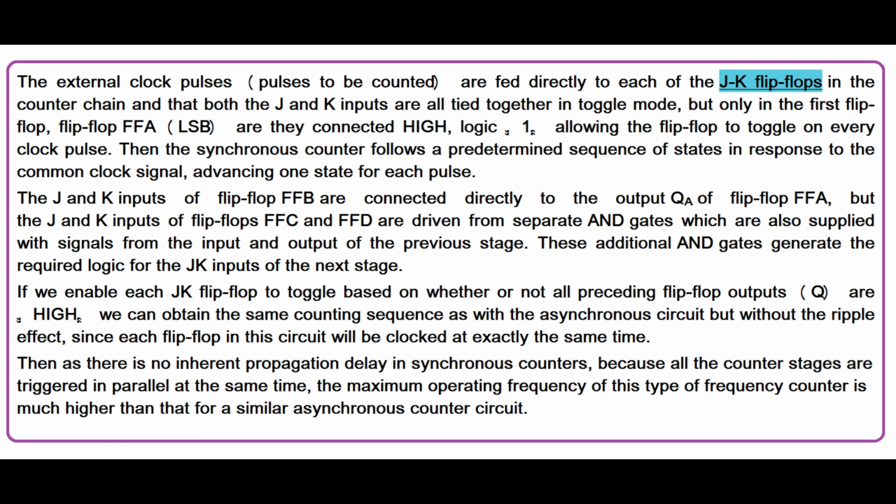FFA, LSB, are they connected high, logic 1, allowing the flip-flop to toggle on every clock pulse. Then the synchronous counter follows a predetermined sequence of states in response to the common clock signal, advancing one state for each pulse. The J and K inputs of flip-flop FFB are connected directly to the output QA of flip-flop